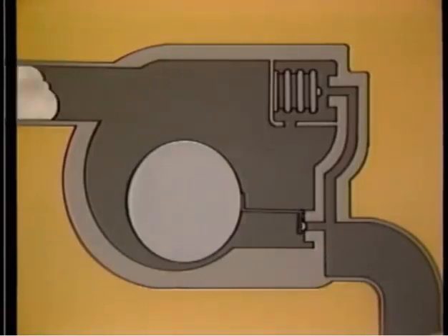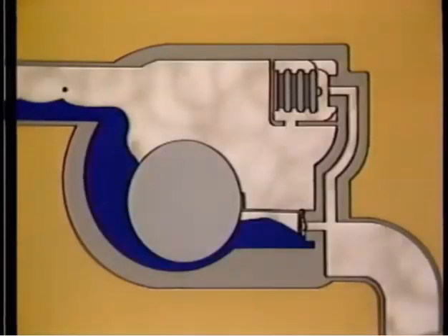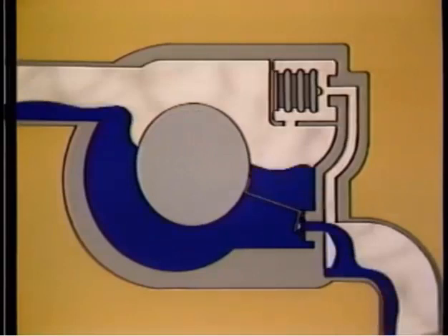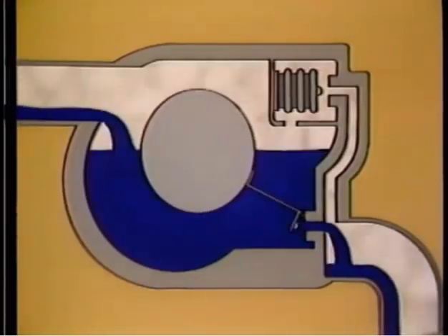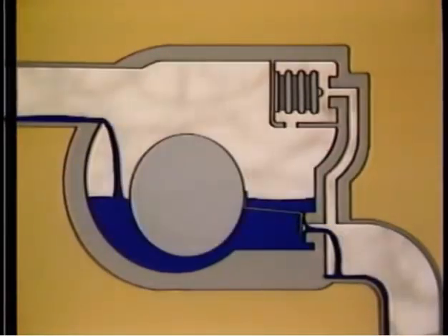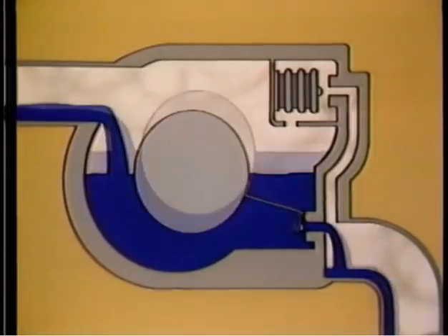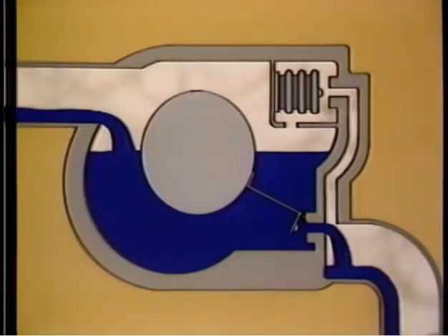Non-condensable gases reaching the trap are immediately vented through the thermostatic valve at the top of the trap. Condensate collects at the bottom of the trap until the float begins to rise, opening the float valve. The float valve normally drains continuously from this point. The condensate level in the trap lowers and raises the float height, thus modulating the discharge flow.